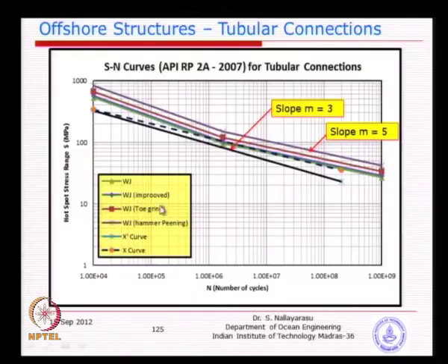If you see here, there are three methods to improve. You can see the higher you go, the higher the stress range it can take. A higher stress range it can take means the fatigue life will be higher. That is the idea behind it.